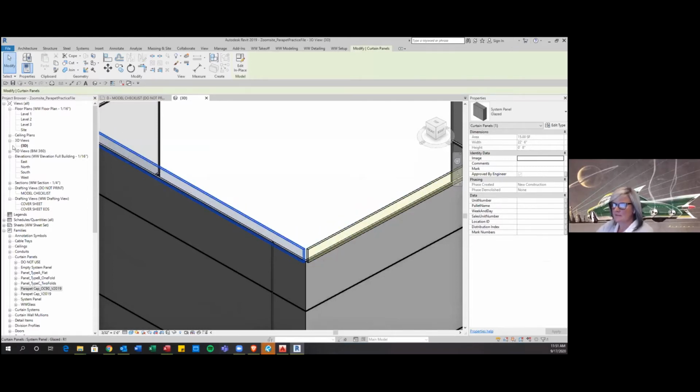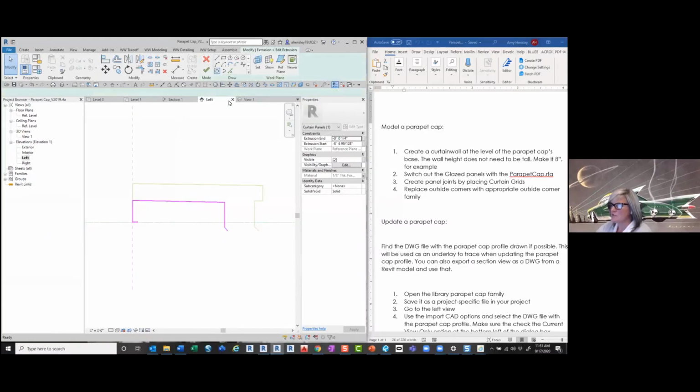So in that left view, you pick on the shape and you come up here, and modify should already be the current tab, and just pick on this edit extrusions, pretty much straight up, the edit extrusion option. And you'll know you're in it correctly when you have this pink outline. It means we're actually in the shape, modifying the profile that will extrude into 3D.